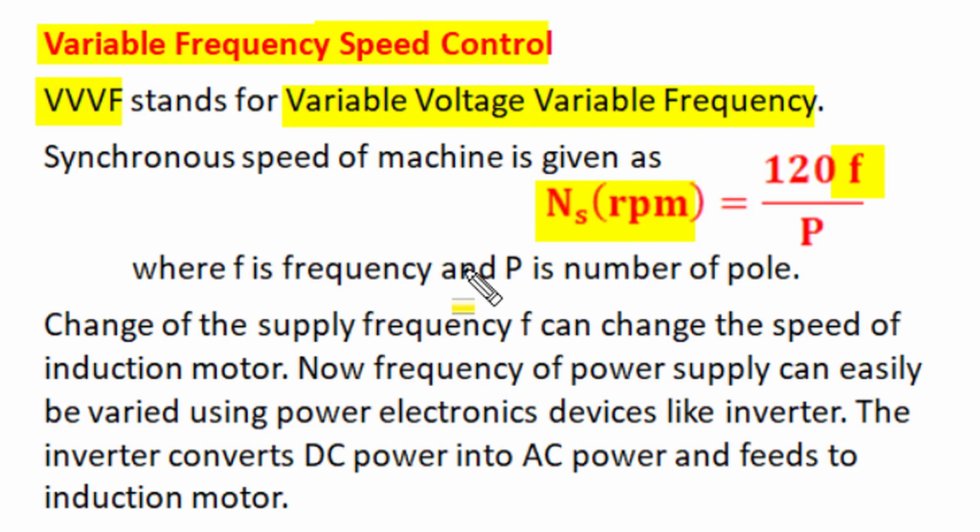But nowadays we can change the frequency of supply easily by modern power electronic devices of the thyristor family, and such systems of variable frequency supplies are called inverters, where the fixed three-phase supply of fixed voltage and fixed frequency is first converted into DC, and this DC power is converted into AC of variable voltage and variable frequency by modern power electronic inverters.